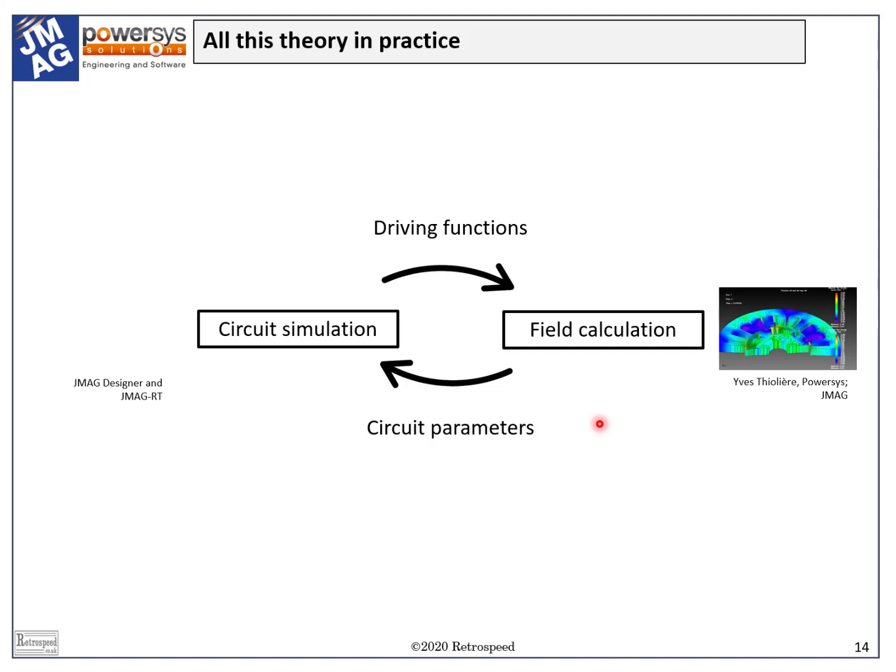The old unified theory was developed to unify the circuit theory of DC and AC machines, but the new unified theory is a software system that unifies the field theory with the circuit theory, a very powerful idea. By incorporating the space vector, it even links itself to the control of inverters, which of course was completely absent in the original unified theory.